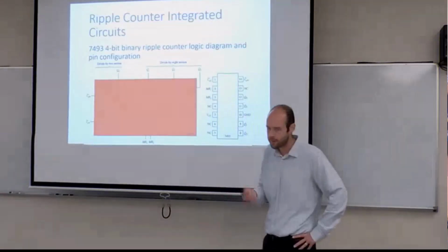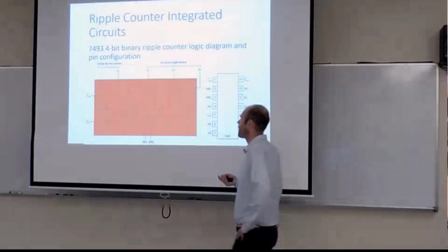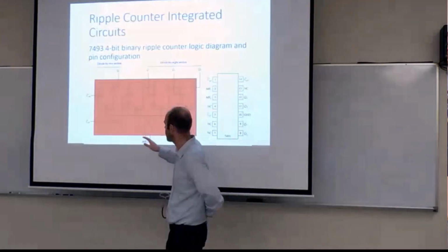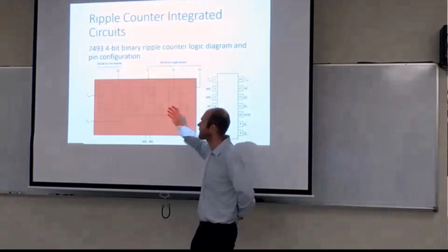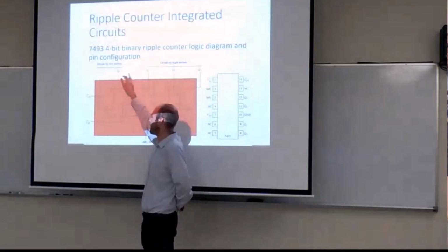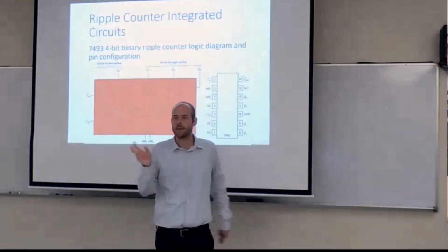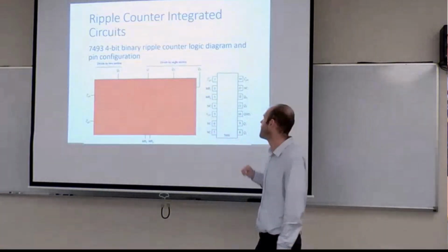In physical chip circuitry, it's a historical element that a lot of physical banks of flip-flops that you buy, at least at small scales, will have a bank of 1 and then a bank of 3 flip-flops. And what you can do is manually tie the Q of the output of the 1 into the clock of the next bank of 3. That's just a historical facet, not a theoretical thing.